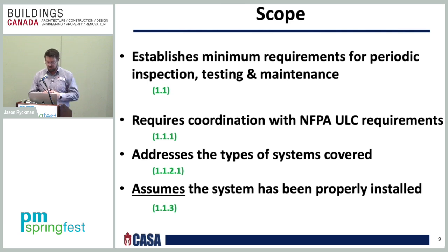throughout the document. You have to note as well that the most important point when using NFPA 25 is that the purpose of the standard is to verify the operational status of the system. We obviously care about the design and installation part of your system, but the whole basis of this inspection, testing, and maintenance document is to make sure that your system is operational, period.